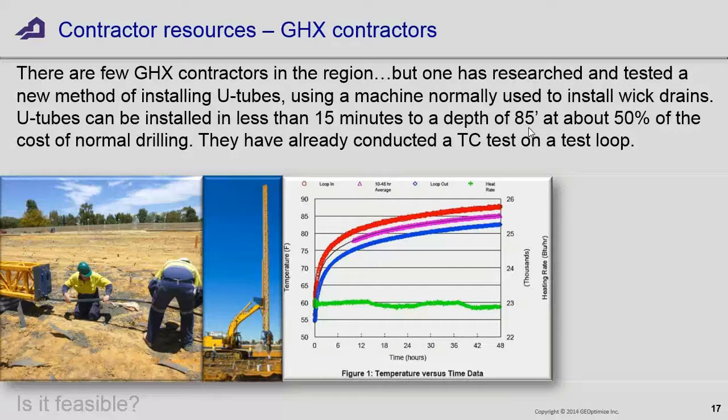And drilling costs were, I think, about $70 or $80 a meter. So not more than that, over $100 a meter. So about 30-some odd bucks a foot. And that's just the drilling. That's not even getting a pipe in the ground or grouting it. So anything that we could do to reduce the capital cost, looking at working with different kinds of contractors that you might not think of otherwise, can help make the system more cost effective.